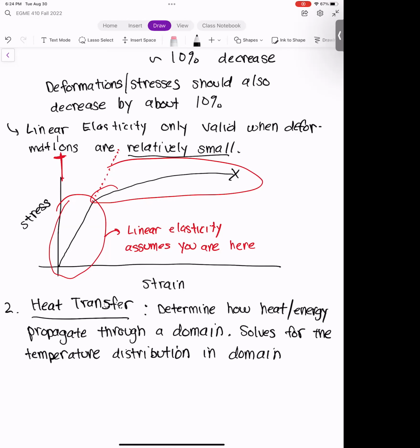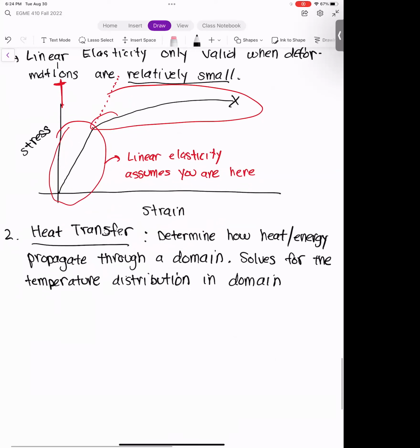And so the heat equation, I think I mentioned it earlier on, but the more basic form of the heat equation looks like this. So this is strictly just diffusive heat transfer, so no convection, anything like that. So this is pure conduction. And so if you solve a static thermal simulation within ANSYS, you're basically solving just a pure conduction problem.